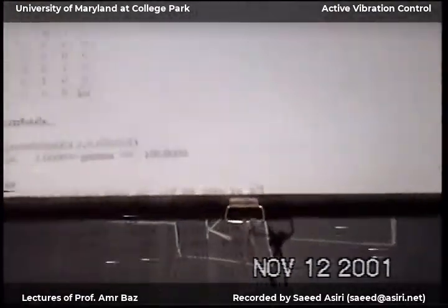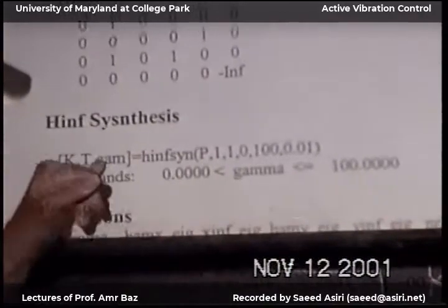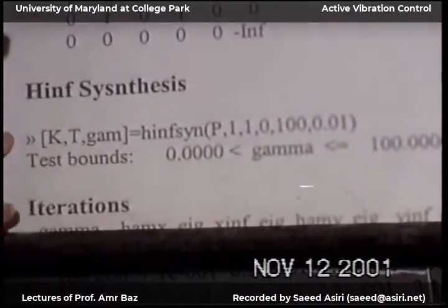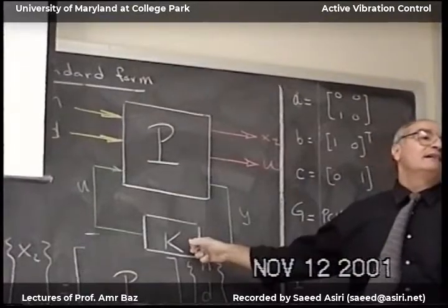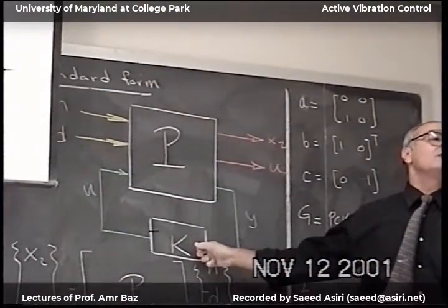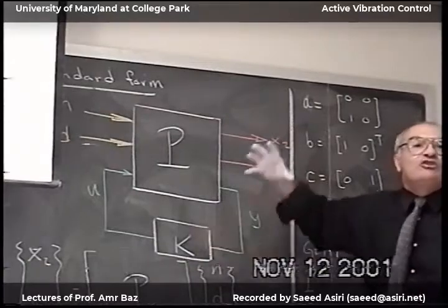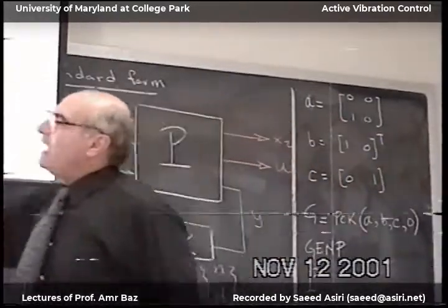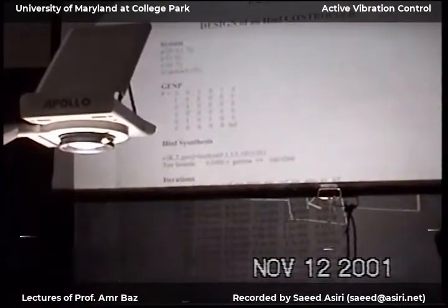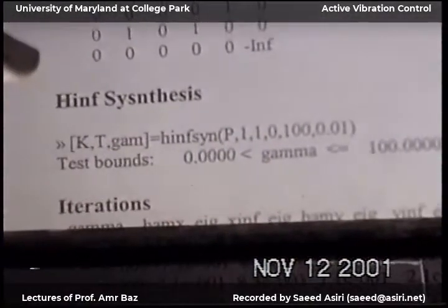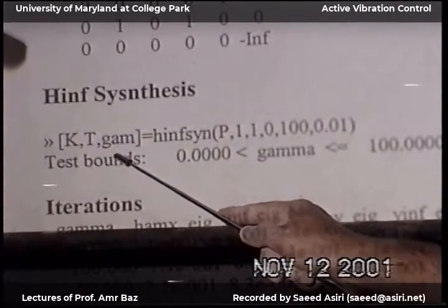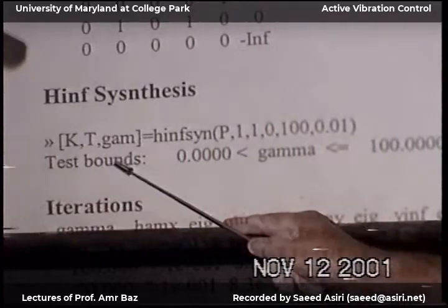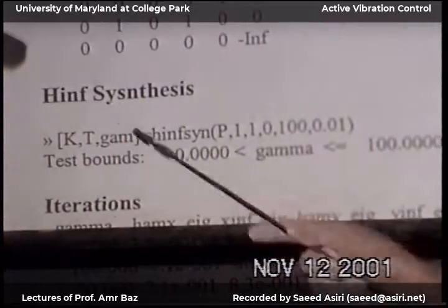And then on the left-hand side, I'm going to call 3 parameters that I'm interested in. The controller gain of the entire assembly. This has the estimator and the H infinity controller, both of them. This is the total K. And get me the co-sensitivity transfer function, so this is GK times I plus GK inverse. And get me the gamma, if you're interested in gamma.